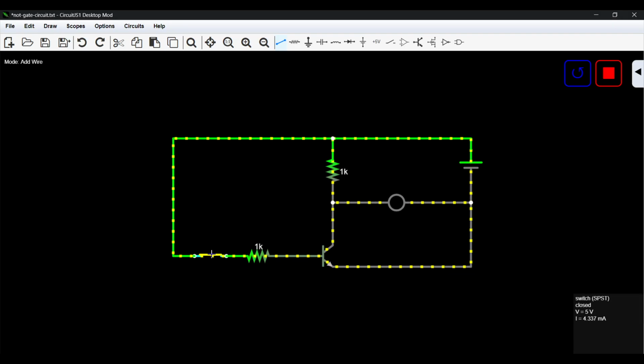And if we open this circuit, essentially now the current flows this way, comes over here to this junction, sees a route this way, and sees another route this way, but this route does not lead anywhere since the base is not activated. Therefore, this is not a circuit.